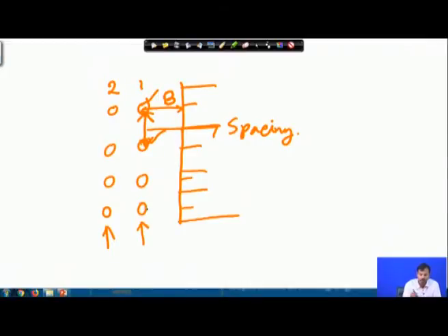After blasting the first row using a delay detonator, your free face will be shifted to this position, and thus the burden for the second row of holes will be this one. Similarly, the spacing will be this one.